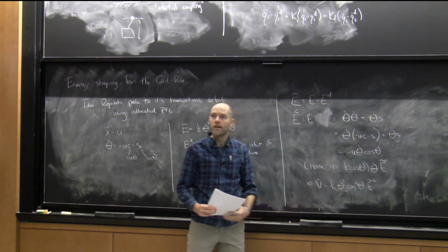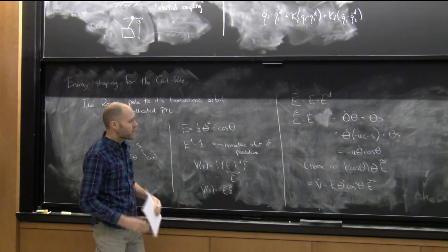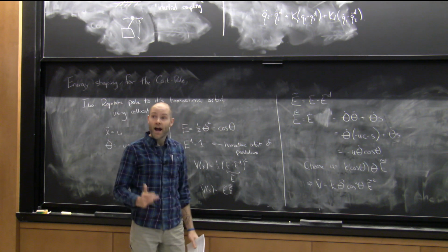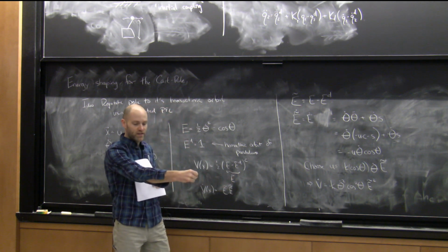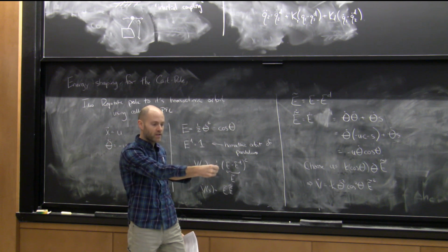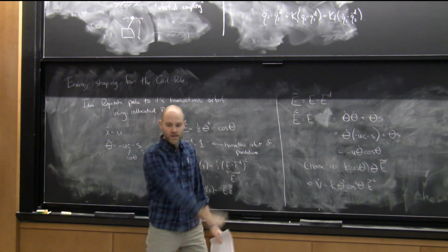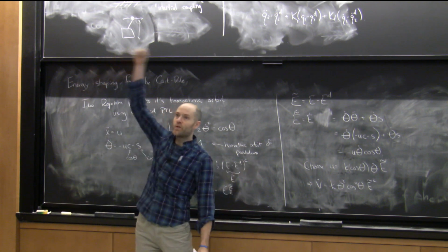Yeah? This feedback, what is it doing intuitively? This theta dot cosine theta, how is it calculating? What it's doing is it's killing the dynamics of the cart, and then it's trying to impose onto the pendulum roughly this same pump up energy and then swing around and go, right?